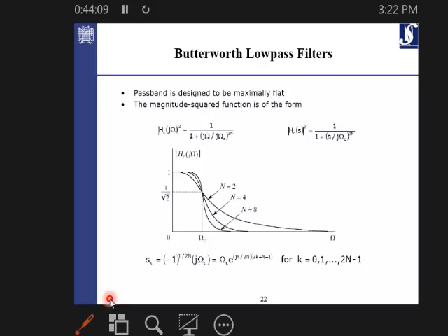We have some options like the Butterworth low pass filter design. So for the Butterworth, the amplitude square is defined like this: 1 over 1 plus (j omega over omega c) to the power of 2n. Omega is the frequency. We can change it from 0 to whatever. And the denominator is actually the cutoff frequency. You set the cutoff frequency to be something, for example, 1.2 kilohertz, and you want to ignore the rest of the frequency band. And it should be to the power of 2n, where n is the degree of the filter.